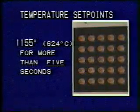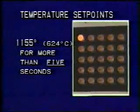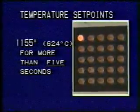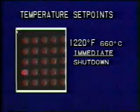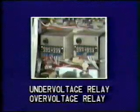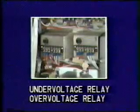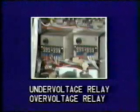The engine has two shutdown set points for high temperature. If the engine's temperature reaches the first set point, there is a 5-second delay before shutdown. If the temperature should reach the second set point, shutdown is immediate. The undervoltage and overvoltage relays monitor generator output and will shut the engine down if the generator's output decreases or increases above their set points.